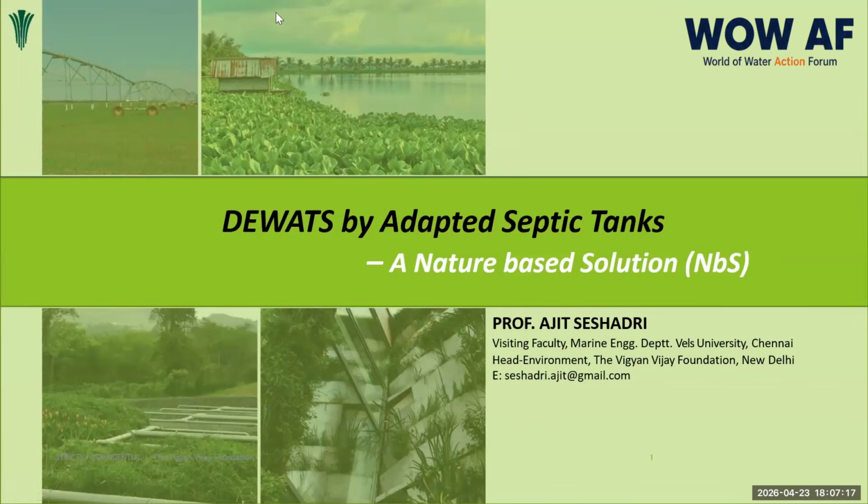Today I'll be talking about DEWATS. The full form is Decentralized Wastewater Treatment System, and I'll be talking about septic tanks, and the septic tanks will be adapted type. Septic tanks adapted means they will have upward flow, and flow from left to right, right to left. There will be baffles in the septic tank, and also separations to have filtration.